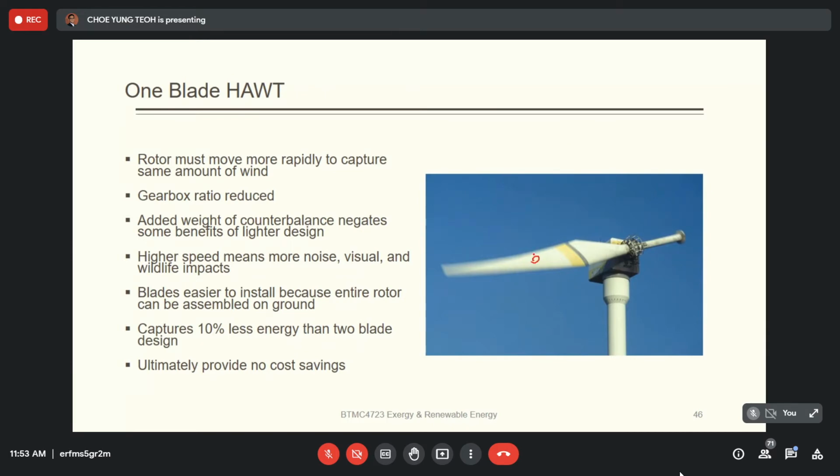And you can see that when you rotate, this is the center of mass, center of gravity. You will have the centrifugal force pointing upward. So it will create a very strong vibration because the centrifugal force keeps changing direction. Now it faces this, later it faces this, later this, and here. So it keeps rotating, keeps changing direction, like an unbalanced mass in the system.